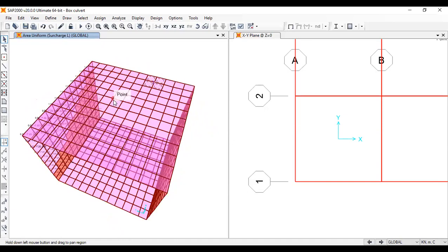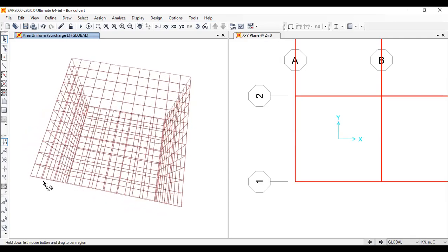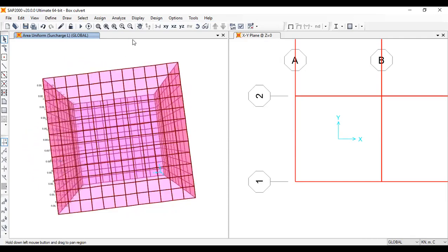The spacing between the axles is 1.8 meters. The dispersion, meaning the load distributed area, is about 1 meter, let's assume. You can always calculate these things according to any code, don't worry.